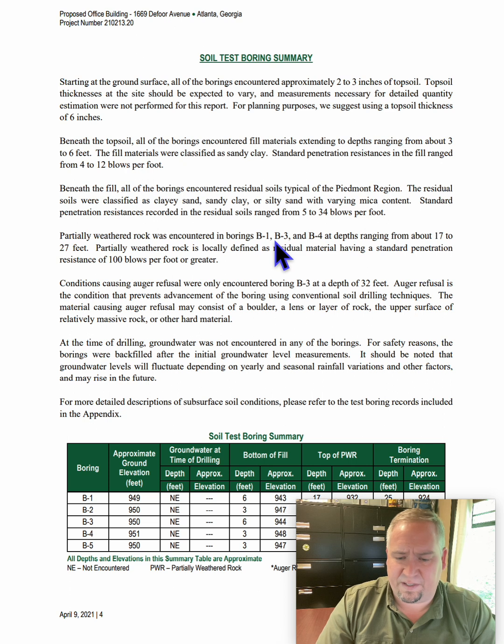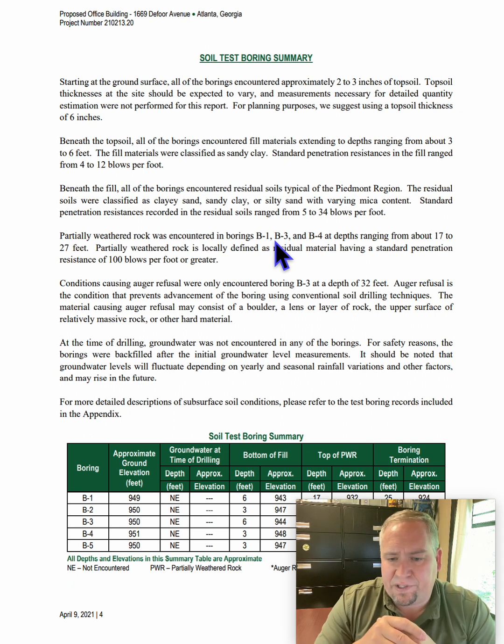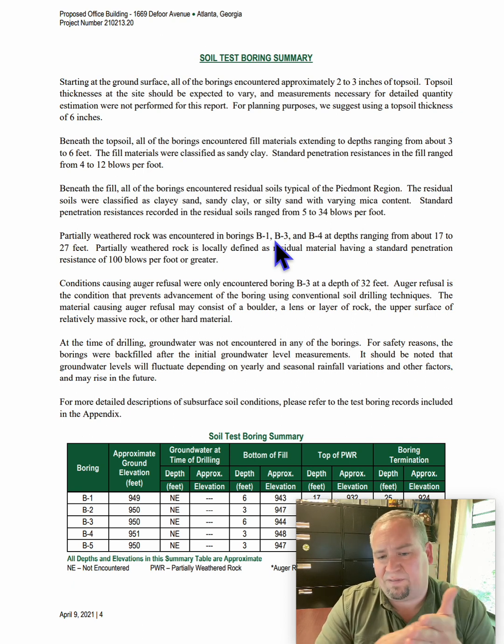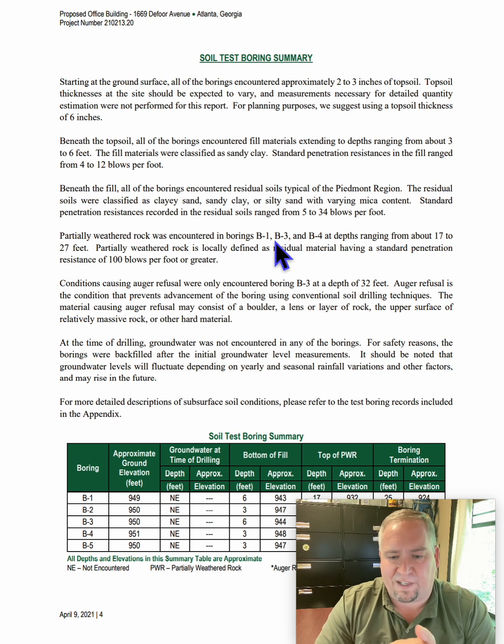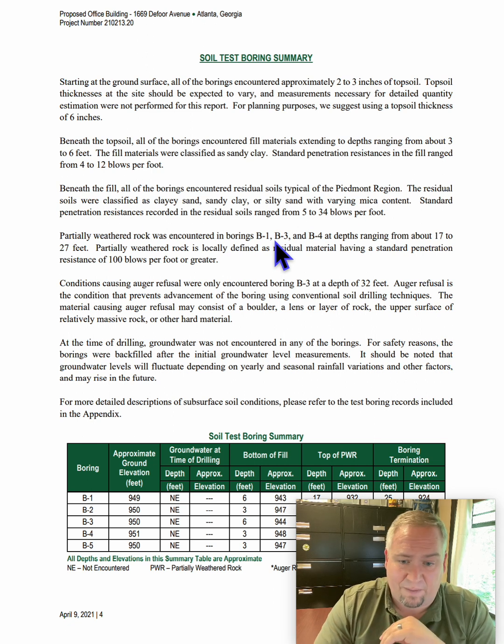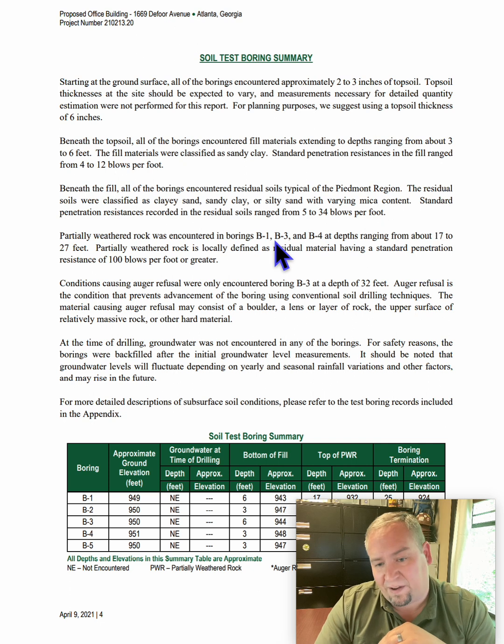And you're going to see the soil piled up beside it where they pulled it off the flights of the auger bit. And usually there's a pin flag. Sometimes they'll have the engineering firm labeled on the pin flag, and they've written on it B1, B2. So when I start a site, I usually like to go find these areas, and I can actually grab a handful of dirt that came out of that area, and get a little deeper understanding of what I've got going on. So those are really good things.